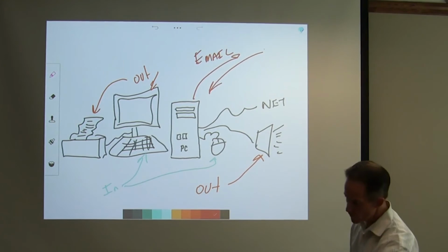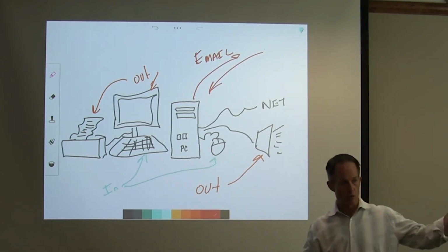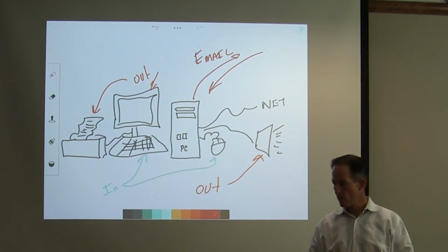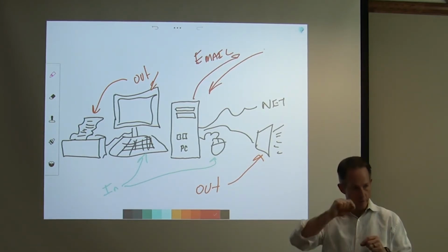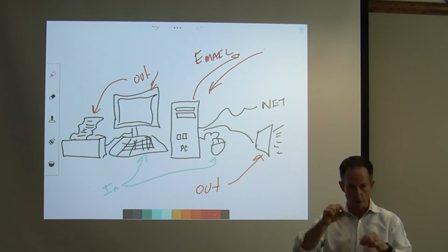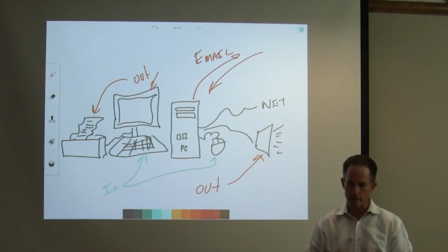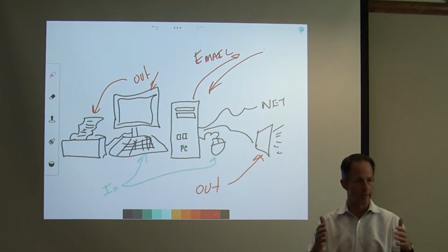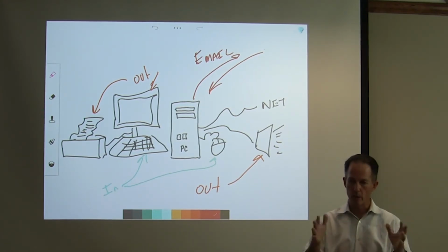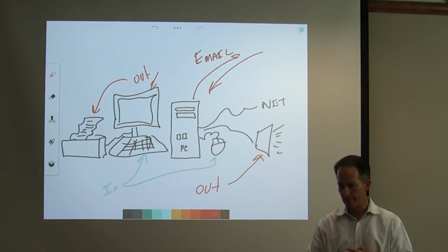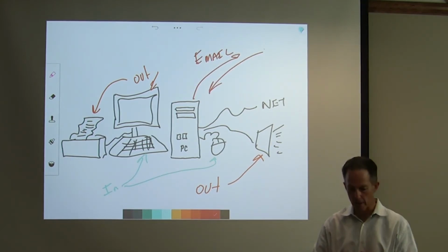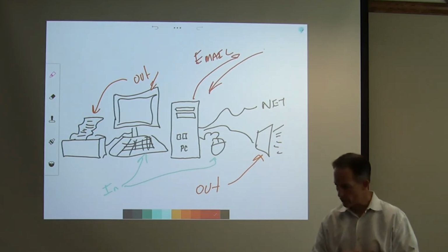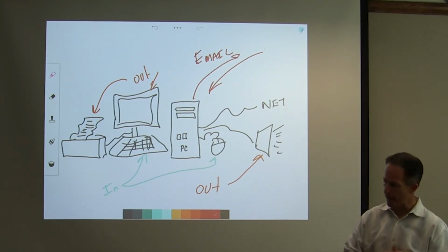Those are the ones we've used for the north plant and the old plant here. They're more expensive, but they're more for critical areas. They give us some override ability, they have sliders and manual adjust right on each one of those modules, and we can add 4 inputs and outputs by just putting in a module, or 8 inputs on a module, and they're very customizable as to what the point definitions need to be. So those work out good. You can do some overrides that way. These don't necessarily have that.